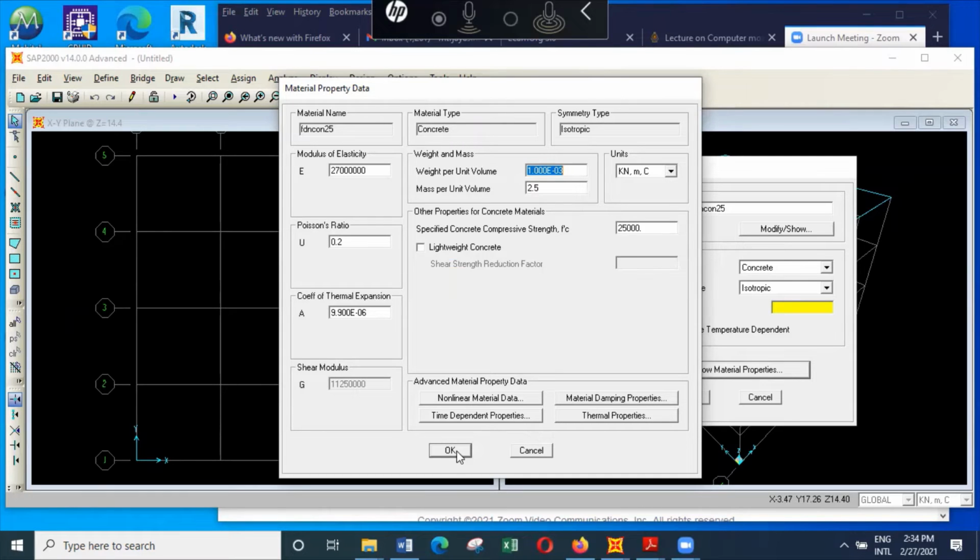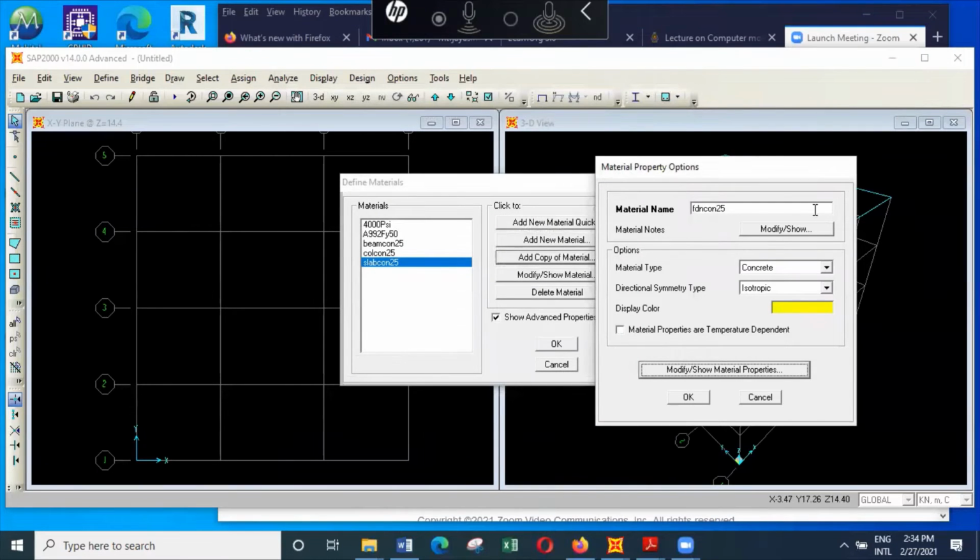One is to take the weight of the foundation into account when you are calculating the total loads on the soil. The other method is using the net bearing capacity method. If you are using net bearing capacity, then there is no need to consider the weight of the foundation when you are doing the foundation design.